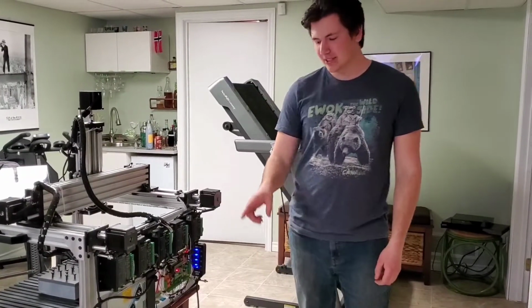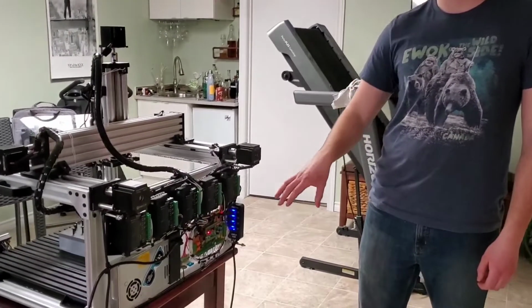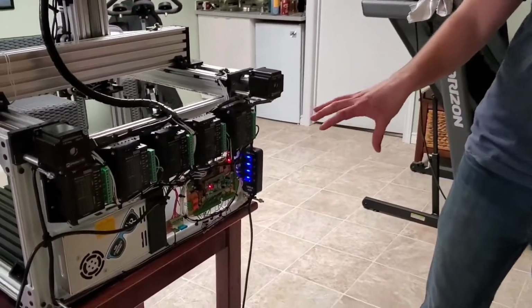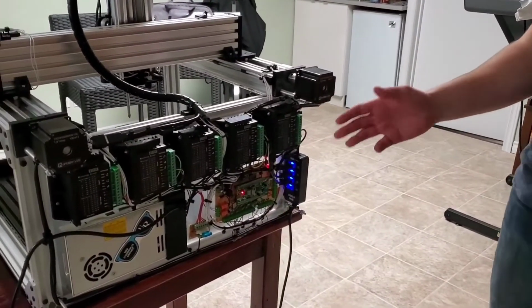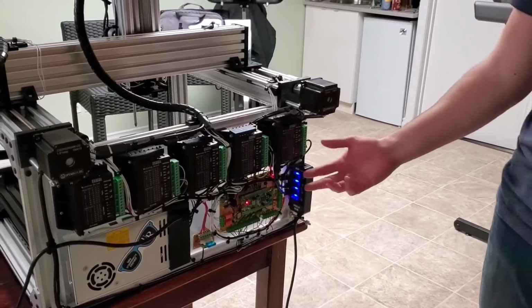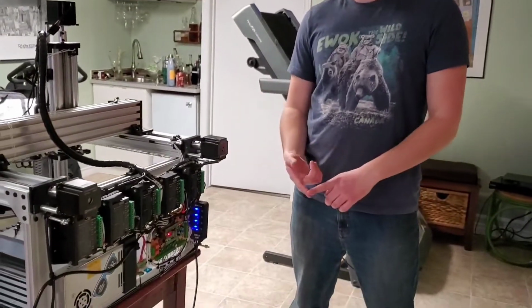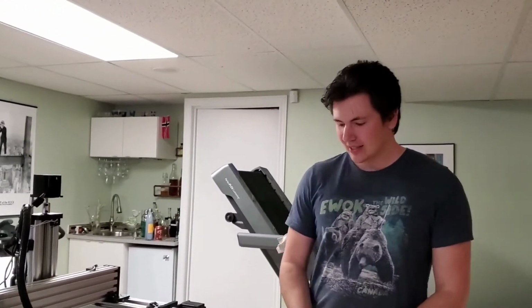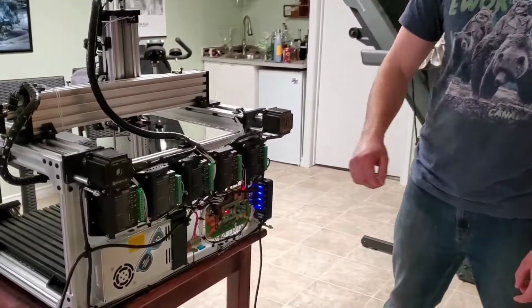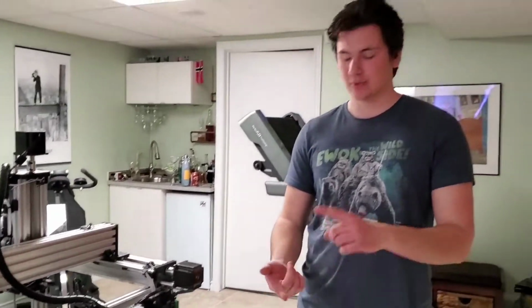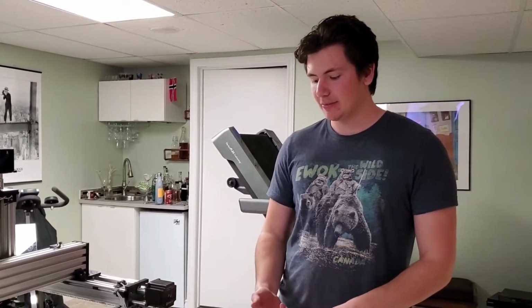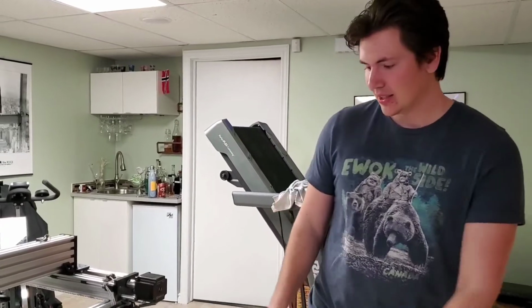Hey, so I'm Matt. I'm going to talk about our microcontroller and our protoboard. This is one of the sections I worked on, and one of the first things we had to decide was what microcontroller we were going to use. So we decided we would go with an STM because that's what we're familiar with. And we decided on the same STM boards that we used in the labs because we're familiar with it, it had enough pins, and it met all of the requirements for being able to control the machine.